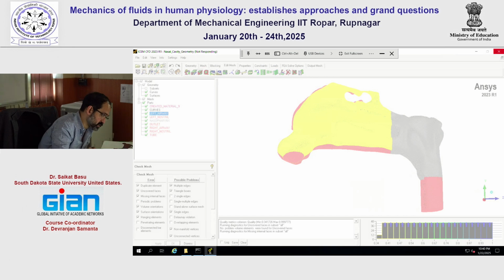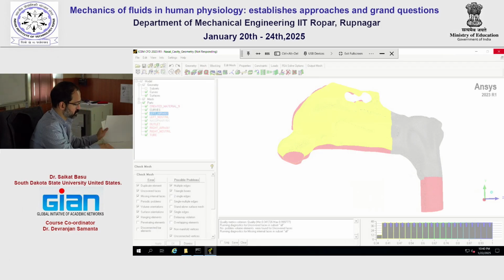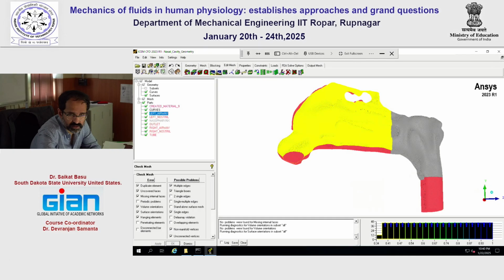Yeah, so I've used 3 layers with the overall height, the total height being 0.1 mm. But you can choose 4 layers as well. But based on the journal that you are going to, you have to justify what you are choosing, and you might have to run a mesh sensitivity study. Sometimes you can cite published works in this domain that this is what has been done and has been tested to work.